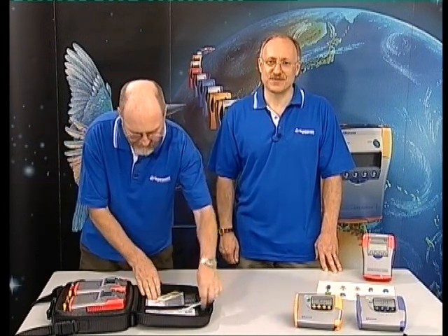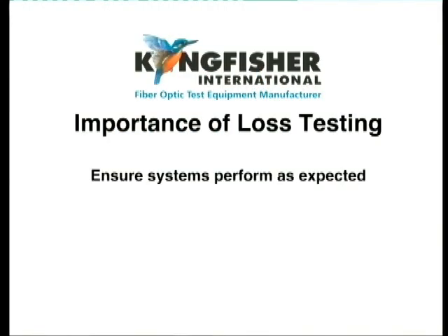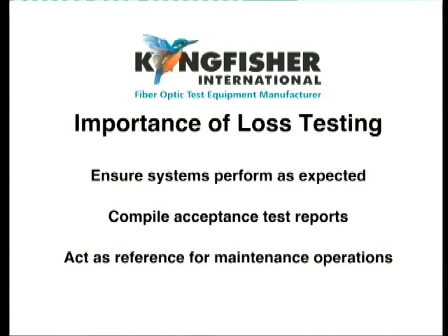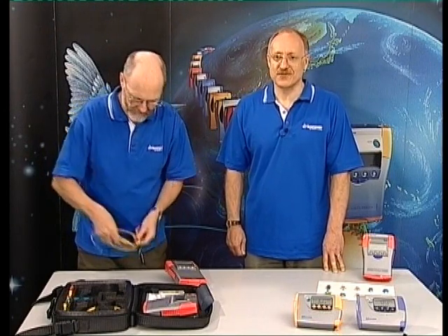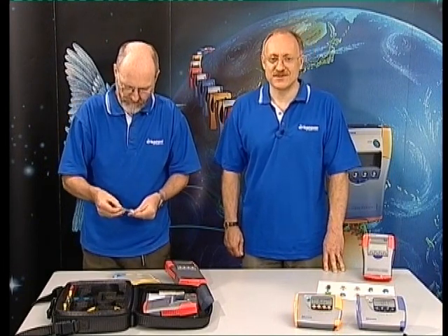the decibel. Loss testing is important for three reasons: to ensure that systems perform as expected, to compile acceptance test reports, and to act as a reference for maintenance operations. So correct testing is an important business issue. Generally, the business value greatly exceeds the testing cost, which in itself is a significant factor.